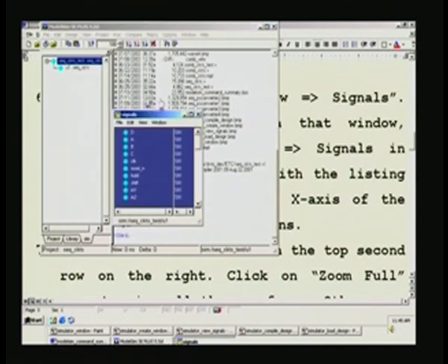So, you have seen precisely the same signals window opening here, and in this you see one view, and that is what we were just reading: view, then wave. Then in this there are three options. One is selected signals, signals in region, a particular region, or you can select some of these signals here, or in a particular region you can select those signals. This will not be an exhaustive list of the signals, and if you want the exhaustive totality of the design reflected, then you should press signals in design. Let us go for this.